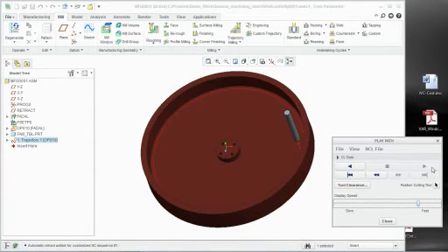Okay, and that really is the power of using Pro-E models with the PTC software, because since they're all connected, if a design engineer at any point throws a change at you, instead of rebuilding all those toolpaths or exporting IGES files and STEP files into other software and then having to recreate them or trying to tie everything back together, as long as it's a change, you have the ability to come in and make that change, go back to your machining software, do a regeneration, and any toolpath that was created against it will update as long as it's capable.